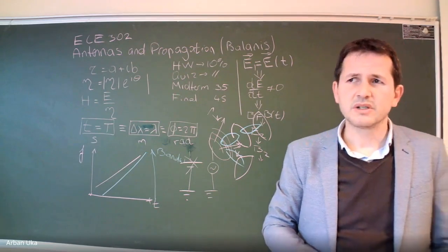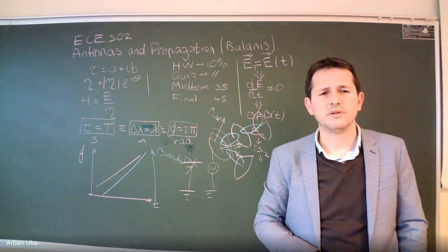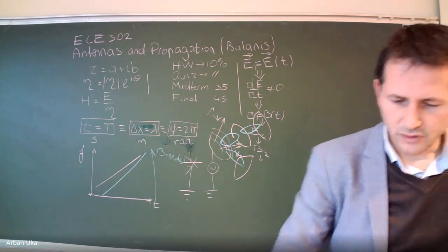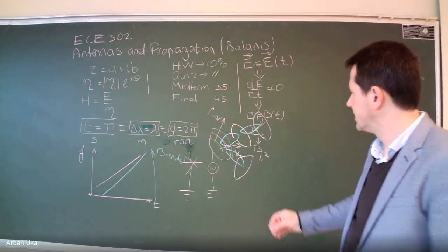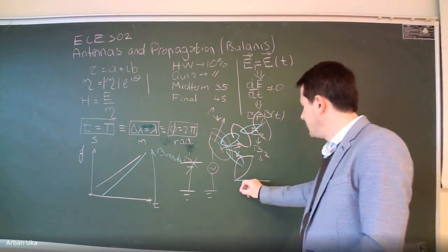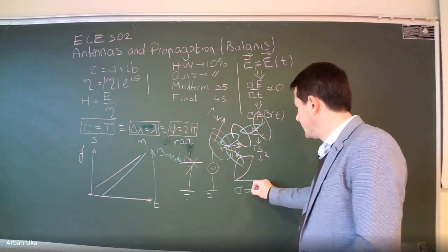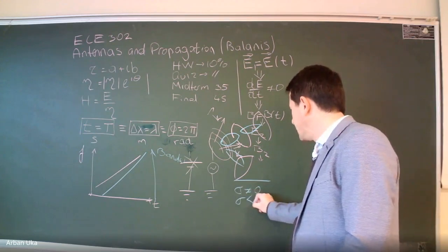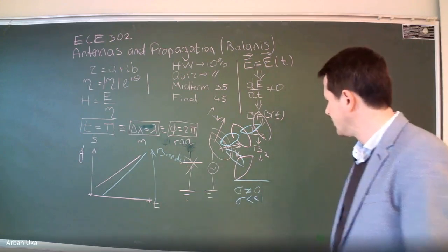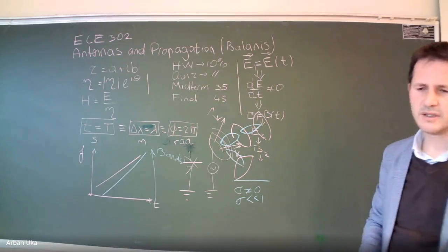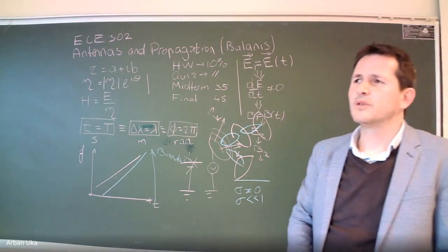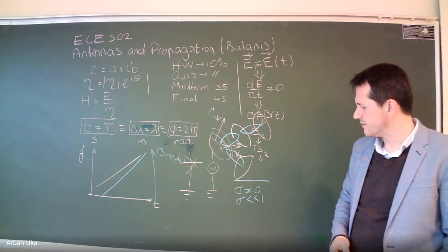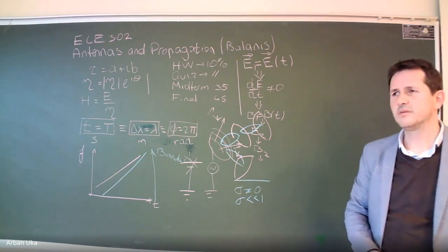Now, skin depth, we traditionally use for materials that have a certain level of conductivity, and when you say certain level of conductivity, we mean this sigma is slightly different from zero. Now, this sigma can be infinitesimally small, but it's different from zero. So once we have this, we are going to have some losses in the system, and even air.